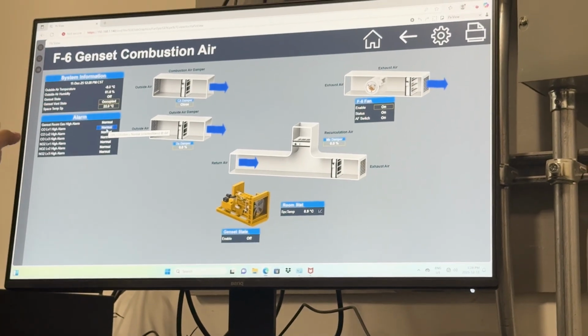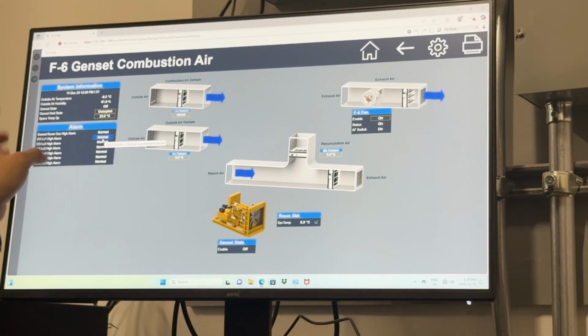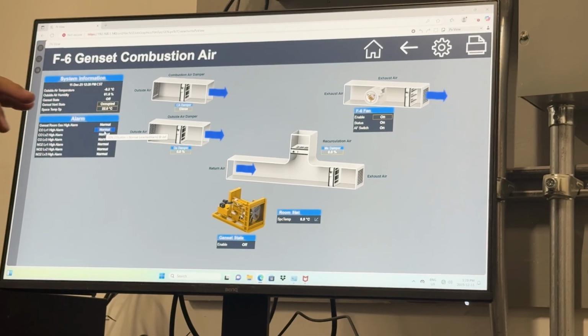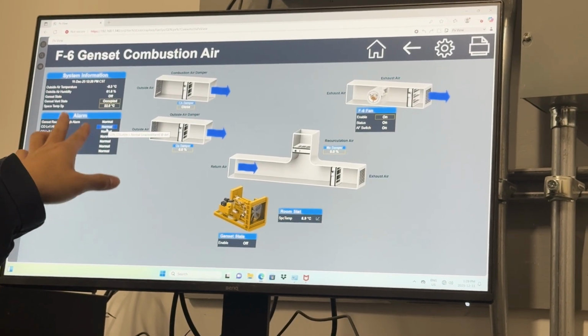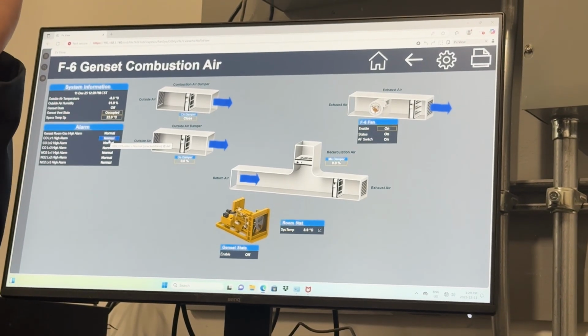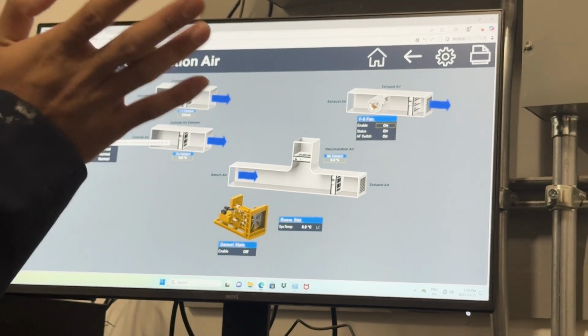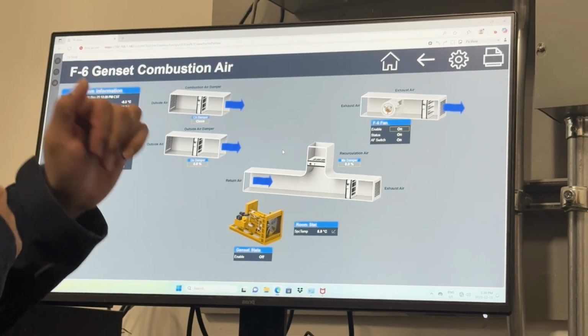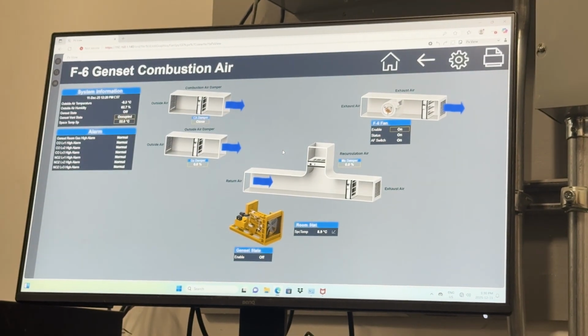Just purging. If we are in level 2 or level 3, an audible alarm will trigger in the electrical room, and it will also show on the BMS. We stay in purge mode and it will still try to purge the room. It doesn't matter if it's full load or no load, as long as the generator is running, the dampers will operate. You should expect them to open.